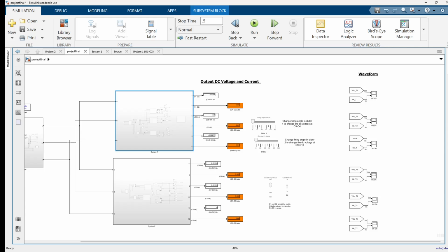However, if you want to have a variable output, we need to use an SCR rectifier, and it will provide voltage regulation at the output, but this will increase the cost of your circuit, and it will also increase the losses due to the firing angle.